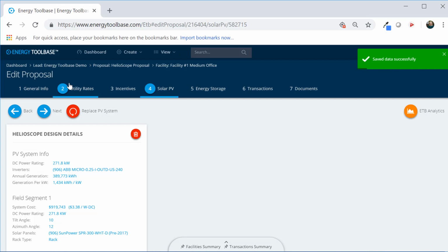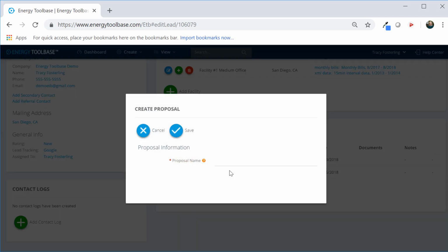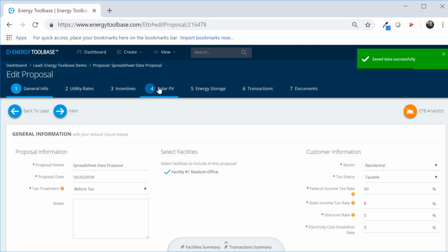We do have a longer form video webinar that shows the process of designing a system in HelioScope and importing it into our platform on our YouTube and Vimeo pages if you want to get a little bit more in depth with this way to upload solar production data. The last way to upload solar production data is through spreadsheet interval data or 8760 data. 8760 data is 1 year of 1 hour interval data, hence the 8,760 data points.